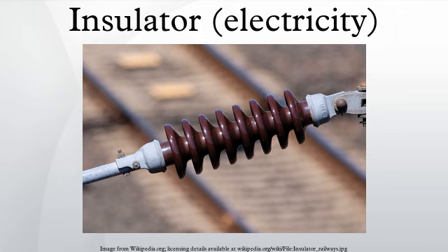Material. Insulators used for high-voltage power transmission are made from glass, porcelain or composite polymer materials. Porcelain insulators are made from clay, quartz or alumina and feldspar, and are covered with a smooth glaze to shed water. Insulators made from porcelain rich in alumina are used where high mechanical strength is a criterion.